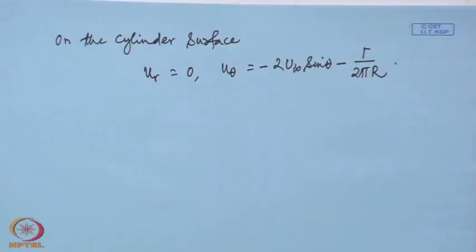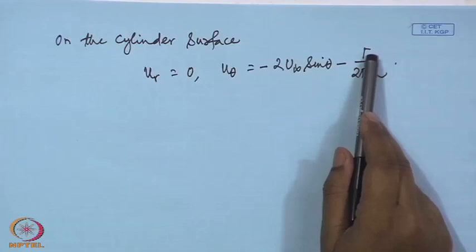The first thing you can see here is that the stagnation points are changed, they are no longer at theta equal to 0 and theta equal to pi. And for clockwise vortex or clockwise circulation, we will see that these stagnation points are coming below the axis, coming to the bottom half, and the location is of course dependent on this value of gamma.